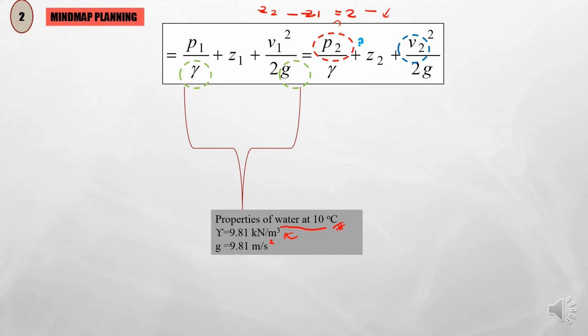So now move to the right side. In order to get V2, actually you can use this supporting equation, if you still remember what this equation is. We covered this in Part 1 and Part 2; this is actually the continuity equation. We need this continuity equation to get V2, because from it we know that the flow rate Q1 will be equal to Q2.